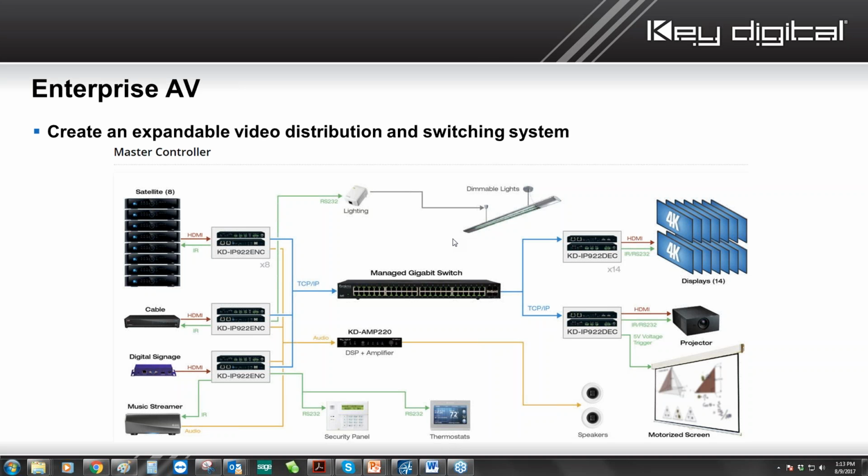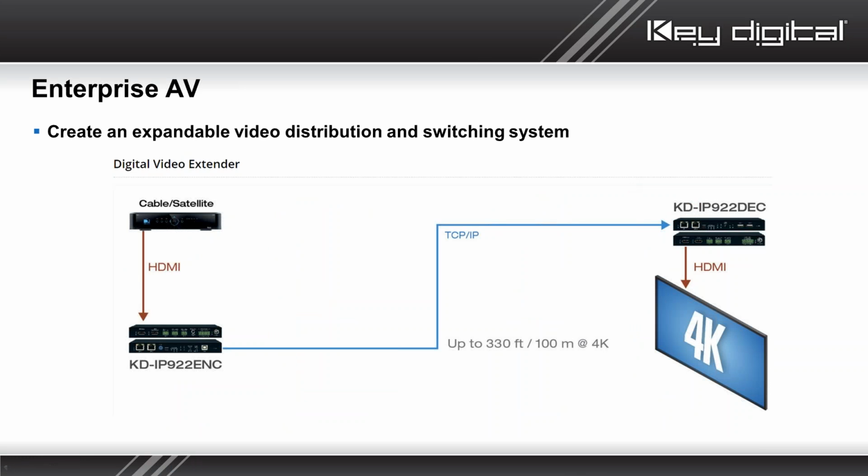The first question is, is the point-to-point configuration for a specific reason or feature, when you can just use the regular balun for the same results? That's a great question. We'll rewind here and take a look at this specific slide. Compare this to an HDBaseT extension, for example. You could use an HDBaseT to do something like this. Absolutely, there's really not a benefit of doing this versus an HDBaseT extender.